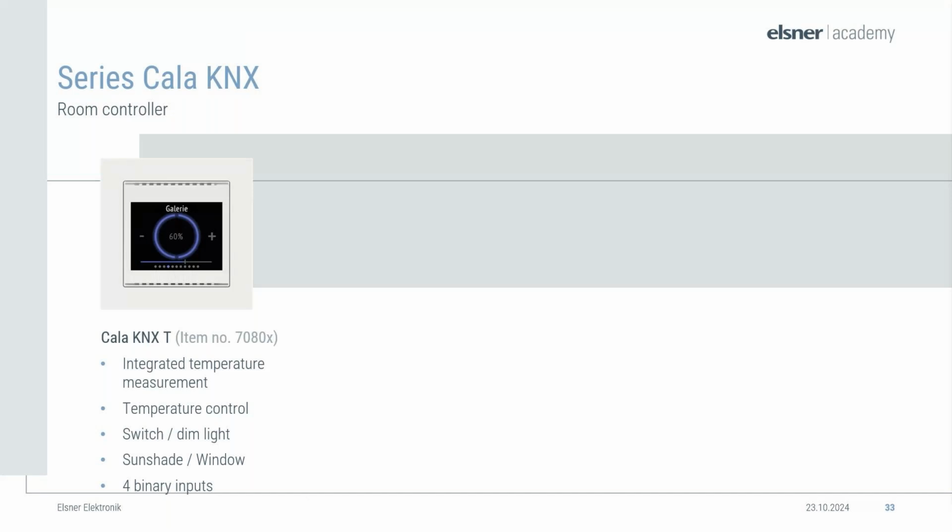Some people call this device the Swiss pocket knife of building automation because that's actually everything you need for a full room automation. You have the shading control, you have the temperature control, you have the lighting control, everything in one device. Another neat little feature is the binary inputs that you can either use for making window contacts usable or also a conventional switch for an overall off.